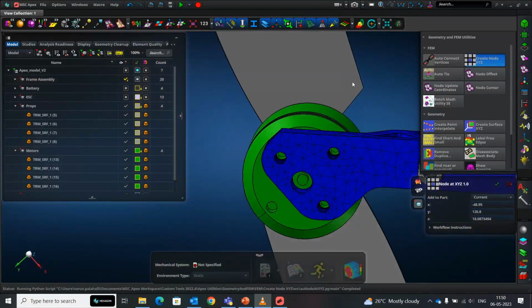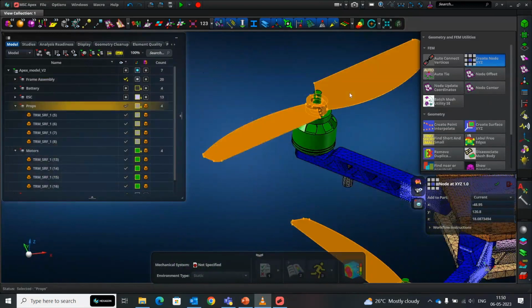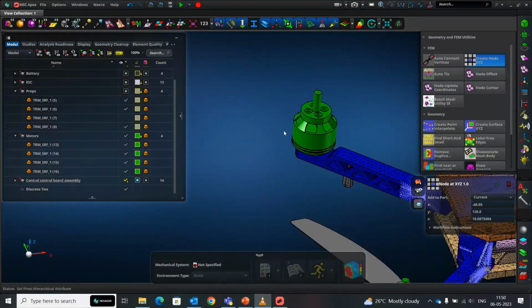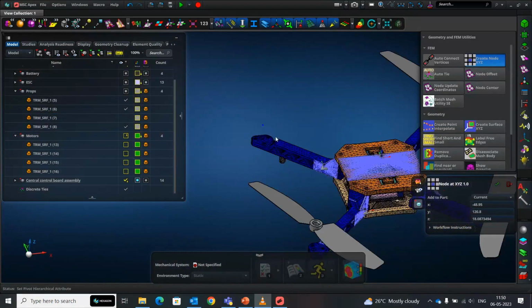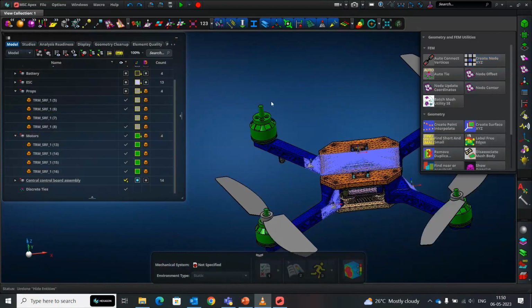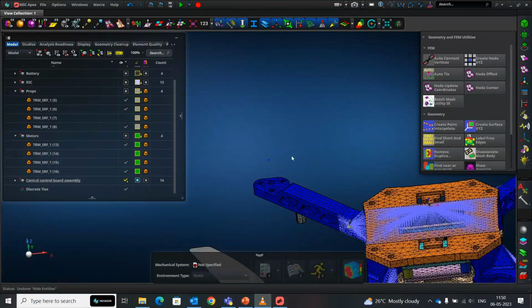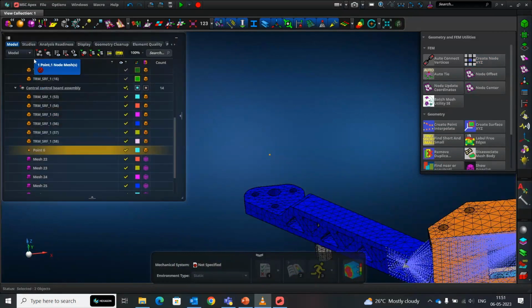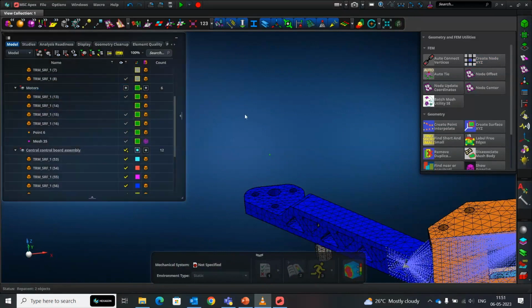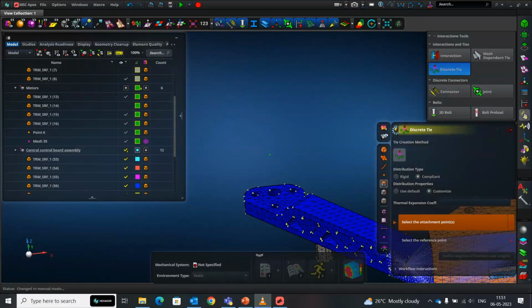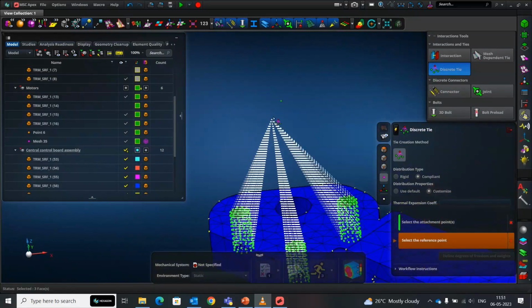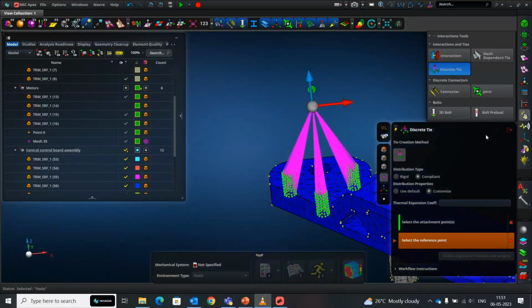And then you can see the regions where this is mounted. I know where the motor is mounting. So this is where your motor mount, whatever connector that you're going to be using. So some fastener points for your motor mount. You can see there are basically 3 holes over there. So that is where I'm going to connect this. I'm going to once again put these 2 points into the motors part, which is not mandatory, but I like to keep all of my corresponding components in the same part. So I'm going to choose these holes where it's going to be mounted. That's where the load path is going to go.